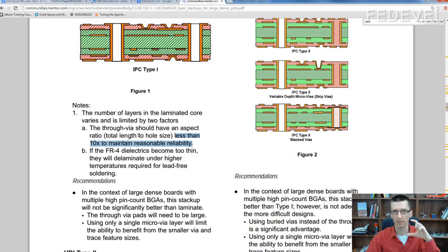Yes. If in your application you use a thicker PCB, 3 millimeter PCB, the minimum through-hole via hole size which you can use will be 0.3 millimeter. And it's even more important for micro vias. I show you.